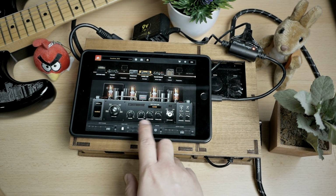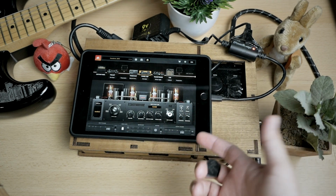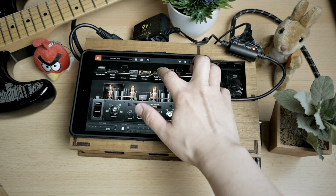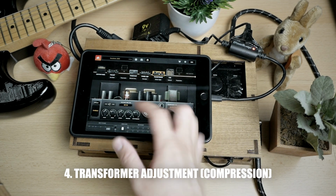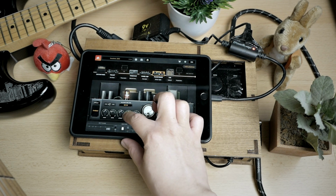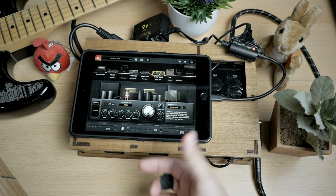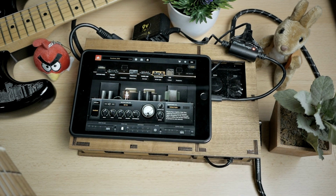I don't think we need to mess with that. The power amp tube is already correct. It's 6L6, so it's gonna sound a little bit American, but on the transformer setting, we're gonna keep it to British style. So with the compression, we're gonna do a little bit of adjustment. We're gonna reduce the release. I don't want to compress the notes for too long. I think the attack is already correct. Just increasing a little bit of the ratio so that it's compressing a little bit harder than what it's supposed to be. And let's check the sound.